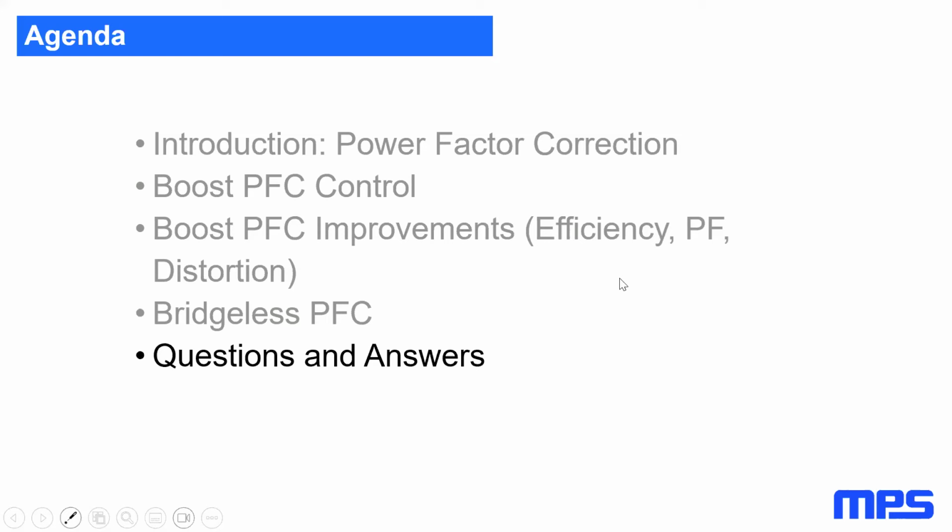Thanks, Nicolas. The next one is, some classical CCM PFC uses a controller IC without V-in sense. Is it possible for totem pole PFC? Because the totem pole PFC needs to control the polarity selection MOSFET, it's really hard to do it without V-in sense.